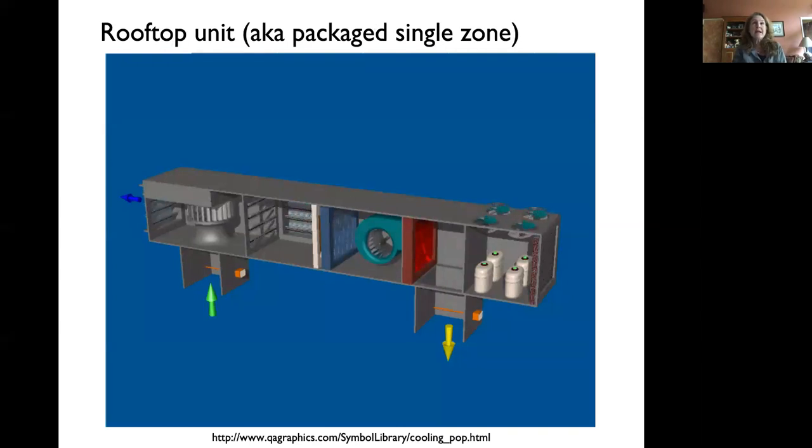So this is an example of a rooftop system where everything's packaged in one place. You see a lot of these, and all of the elements are in one thing. They're delivered, they're popped onto the roof. Simple. If you're taking BART, you look around Oakland, you see these on top of all of the warehouses. So the advantage is that it's got a cheaper first cost. They're generally pretty awful from an energy point of view, however.